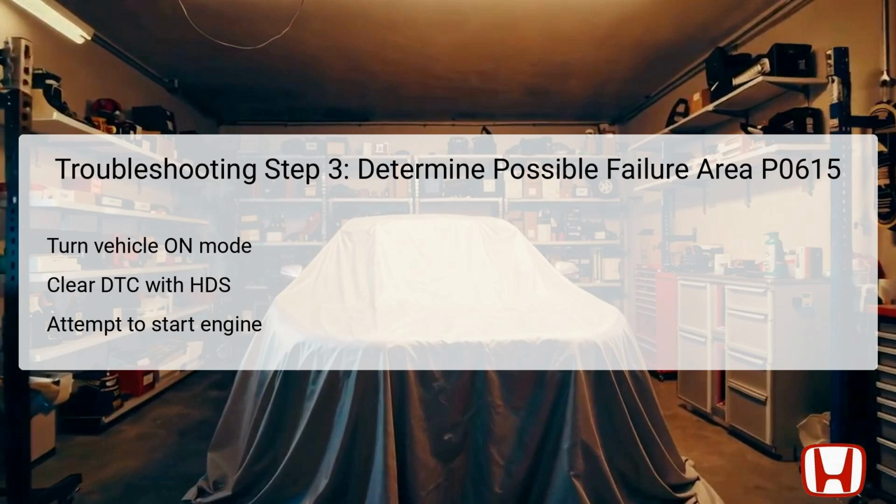If the engine starts successfully, it is indicative of a potential intermittent problem, directing you to further diagnostic steps. However, if the engine fails to start, you will move on to inspect specific critical circuits, beginning with the wiring associated with the start diag line.